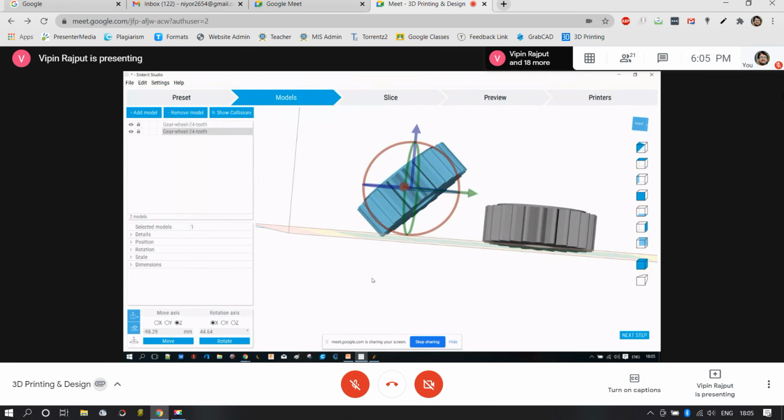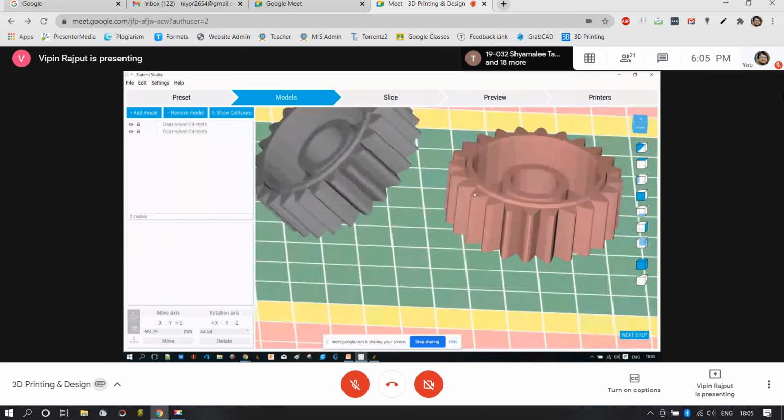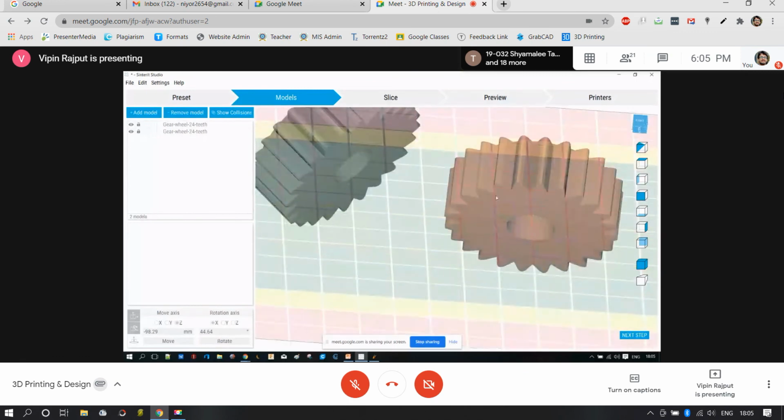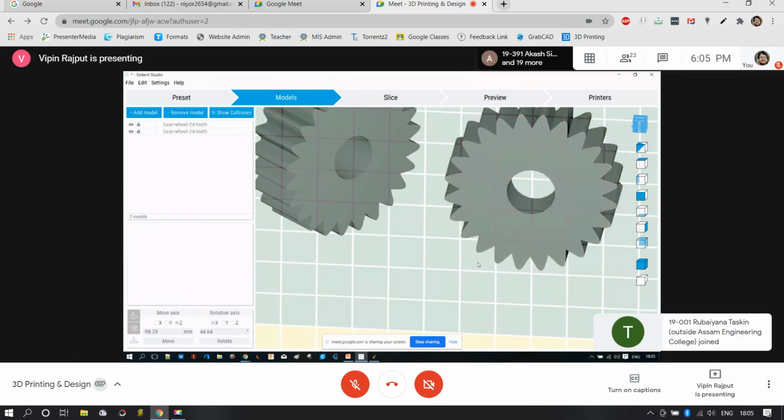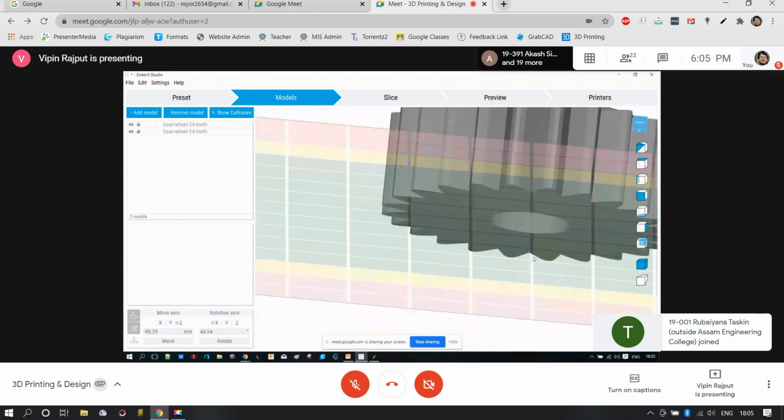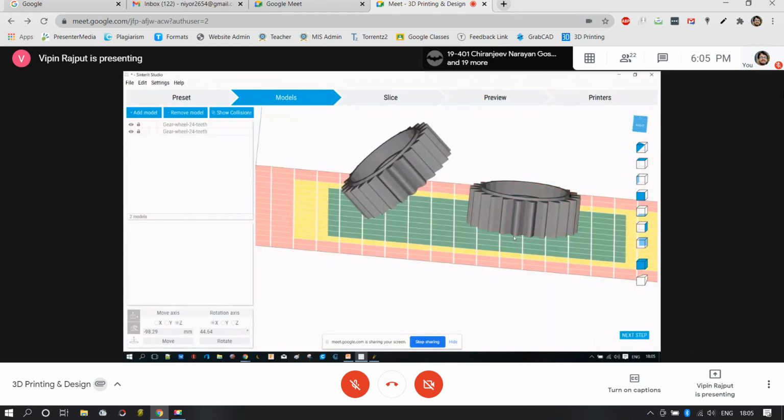Yes, sir. Okay. So the reason is, if a model is flat enough, a very big amount of surface area will be exposed to the laser. Thus it will have to throw a greater amount of laser over the particular powder, and the particular object will be formed. So let's say the model was supposed to be constructed from this point till this point. Within that process, multiple material depositions were happening over the model, and then it was sintering. Then again, one coat of material came over, then it sintered. So binding actually took place.